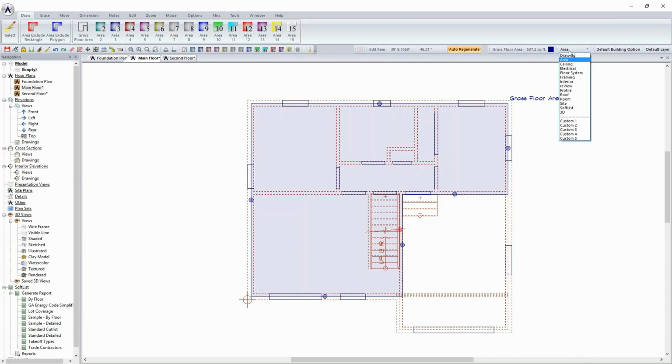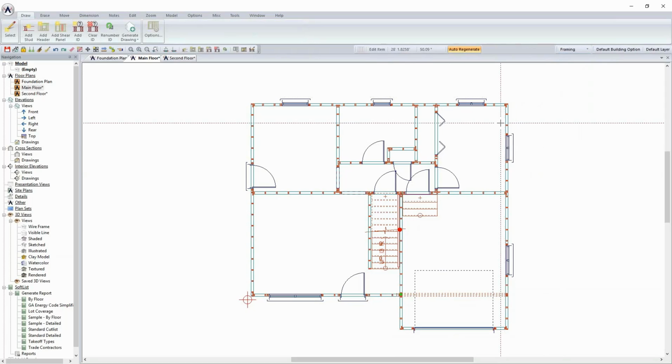So again, just using this as a checklist: the drawing mode to get drawable items in there, the roof mode, which I talked about, or the ceiling mode, which allows the insulation. Framing mode is one of those modes that we tend to just take for granted and bypass, especially if you're not doing things like wall framing diagrams, etc. But if you take the time to go in and modify your framing settings or options within the plan, your framing, in other words your stud count, will be accurate.